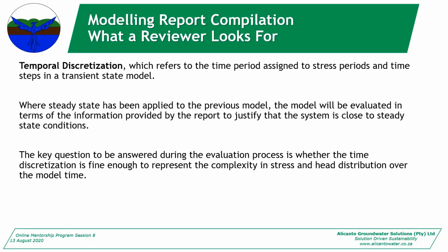Yes. Just a question on that one. Suppose you have got a situation where the recharge in summer is different from the recharge in the wet season or in the rainy season. Then apart from that, you have got 2 aquifer systems. You have got the one which is open underlain by the one which is confined. How do you deal with those in terms of stress periods and so on? Maybe you can help with that.